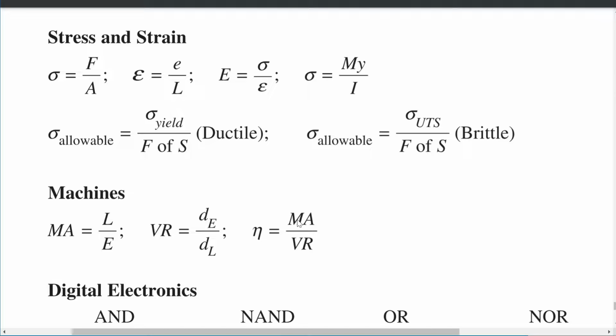What they're talking about is that a machine will be rated at a safe operating level, and this is not just in terms of actually injuring people and causing harm, but also harm to the machine, so that the machine might start being more likely to behave outside its tolerance range, might start having unacceptable levels of wear if you're overclocking, if you're making the machine operate at more than its rating.